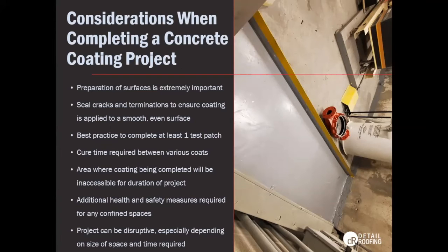It is best practice to complete a test patch prior to completing the whole project, especially if the area being completed is a larger square footage. You want to ensure that the product that you're using is going to be compatible with the surface that's there, especially in cases where you're replacing an existing coating and not going on top of just bare concrete.